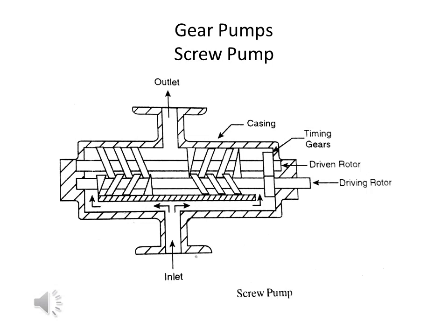and the oil will move along the helical grooves of the driving and driven gears, and thereby it gets compressed and goes to the outlet through the center port, the top port. The compressed, that is the pressurized, oil will get into the outlet to the system, the hydraulic system.